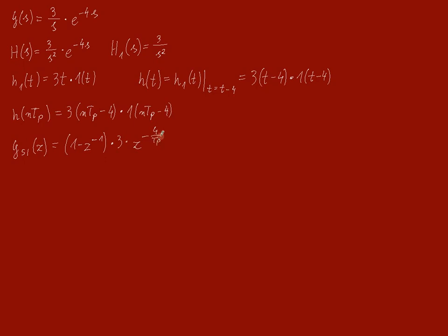If a specific sampling time Tp is given in the text of the task, it should be substituted at the beginning or end of the calculations. And if no specific value has been given, we leave such a fraction. It may also happen that the delay will have Tp at the beginning, and then it will shorten at this point. Z variables need to be multiplied.